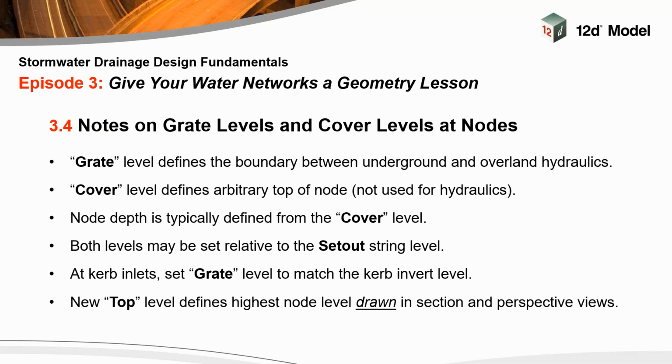The cover level, on the other hand, defines an arbitrary top of the node. It's not used in the hydraulics, and it's really up to you where you want to choose to set that cover level. It doesn't have an effect on the hydraulics, but what it does do is the cover level is typically used to measure the depth of a node from.